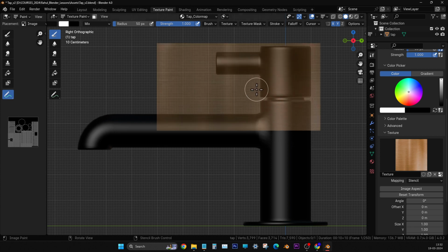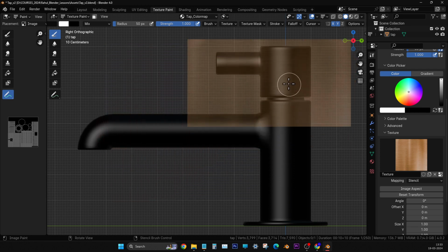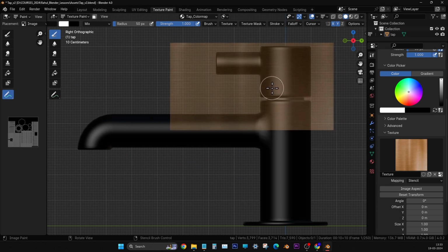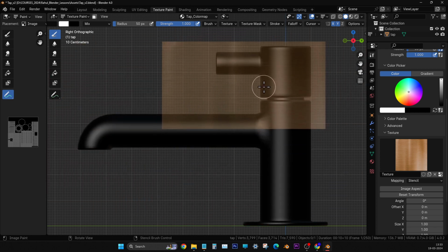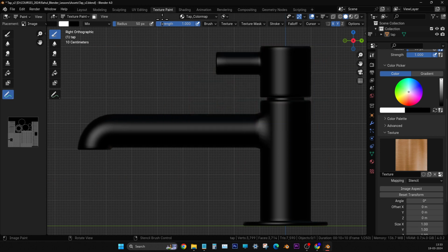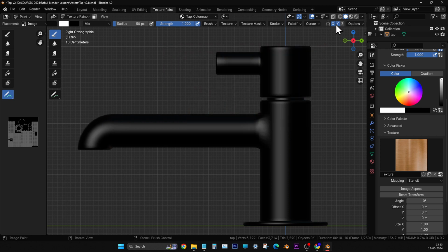Right. Now on the right side I am going to do the painting. You know very well that the stencil image can be moved and placed on any portion of the tab by clicking the right mouse button. I am using the right mouse button and moving the image. Right. Now I am going to paint it. Color map is ready, color slot is ready. We can see the radius is 50 pixels, that is the brush size, and strength is 1 so that it will completely paint, and the symmetry XY is on.